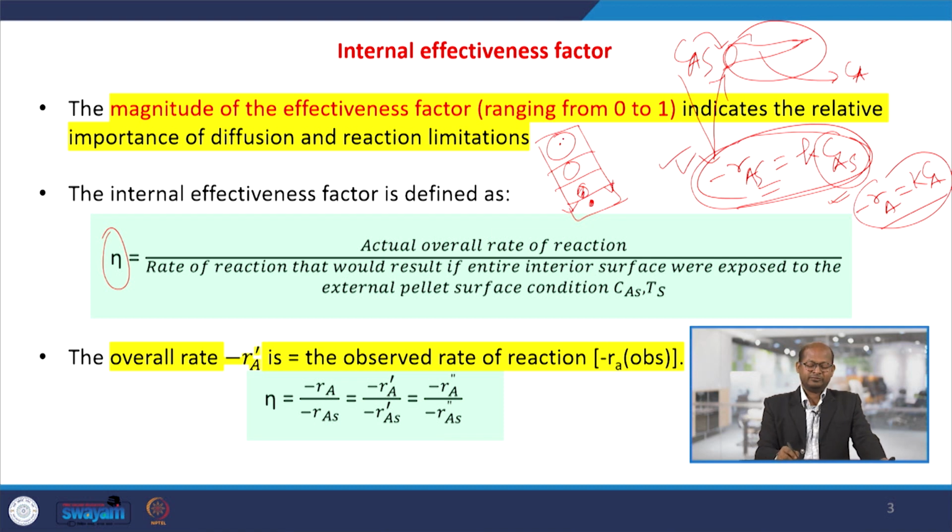But in the real case we have to give the catalyst a particular shape and a particular dimension or diameter. Once the dimension is fixed, pore formations and pore distribution inside the catalyst would differ, so the rate would be different. Based on the effectiveness factor value, we can say whether the rate we expect is coming or not, or whether there is diffusion or not.